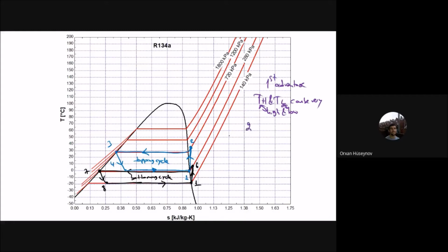And the second thing here is that it is very similar to intercooling. If you have not used the cascade refrigeration system, what you would have to do is go along this line. So you can see that this one is 2 prime. So without cascade, very similar to intercooling, you will have that H2 prime, the enthalpy at 2 prime.